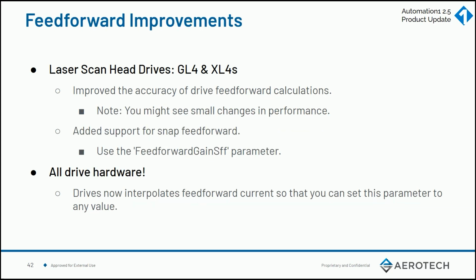We made feedforward improvements in 2.5. The laser scan head drives, the GL4 and XL4S, have improved the accuracy of drive feedforward calculations. And this might show you some small changes in performance. Pay attention to this as you upgrade to 2.5. If you're currently using laser scan heads, see how this changes your program. If this creates any issues for you, please don't hesitate to create a GTS issue.